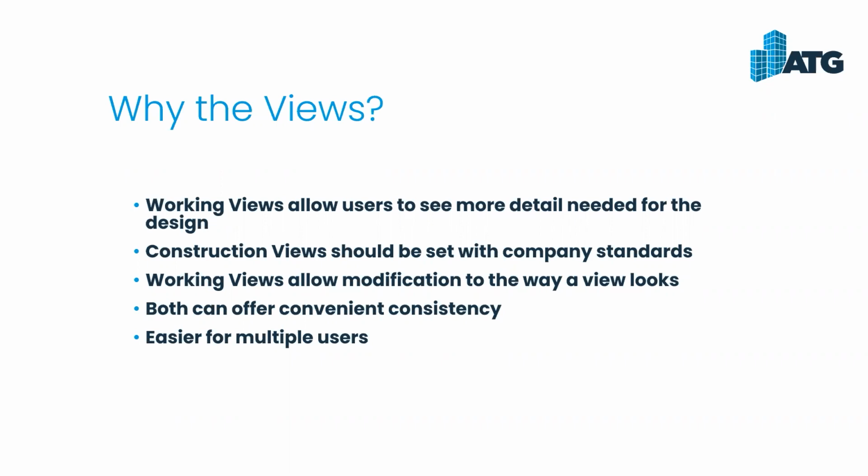Now the working views, we can allow a little bit of modification to the way that view looks. Obviously, you can have multiple people working in a working view. People may want to see things a little bit differently from occasion to occasion. It's easy to go in and switch. A lot of times, working views may not have a view template. Some people will have a working view template assigned that has quite a few things on, but allows it to be tweaked here and there.